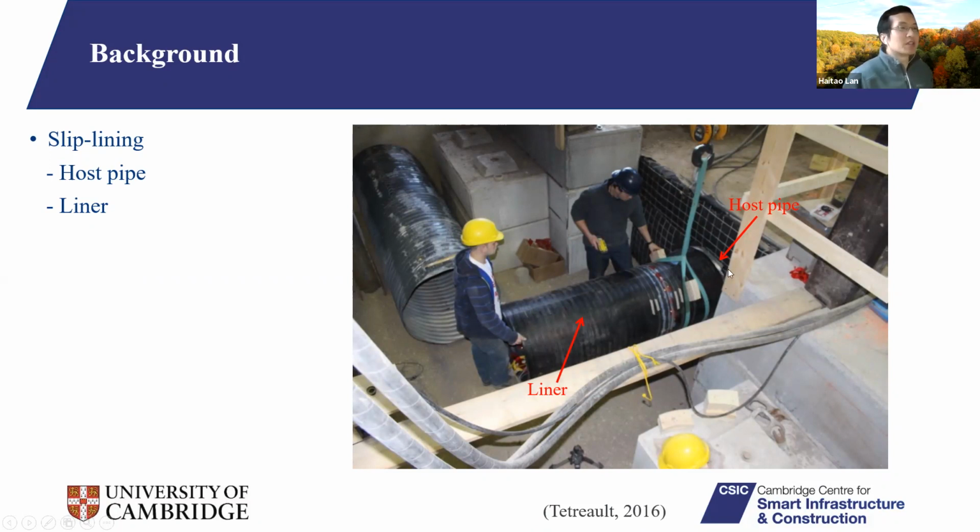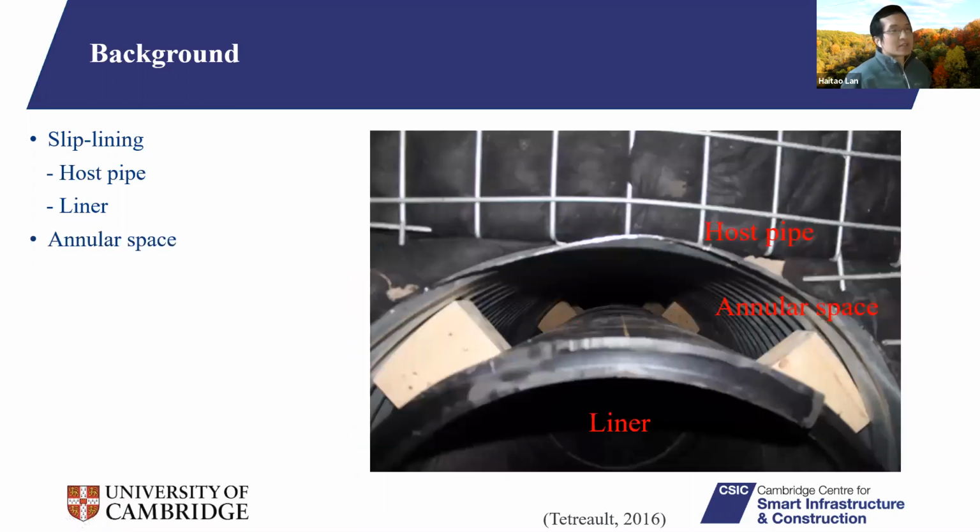So here you can see that's the host pipe. They already buried it in the ground. And that's my colleague Caleb. He just helped the technician move the pipe into the host pipe, or slip the liner into the host pipe. After that, you will see an annular space between the liner and the host pipe. So we need to use the grouting material to fill this annular space.